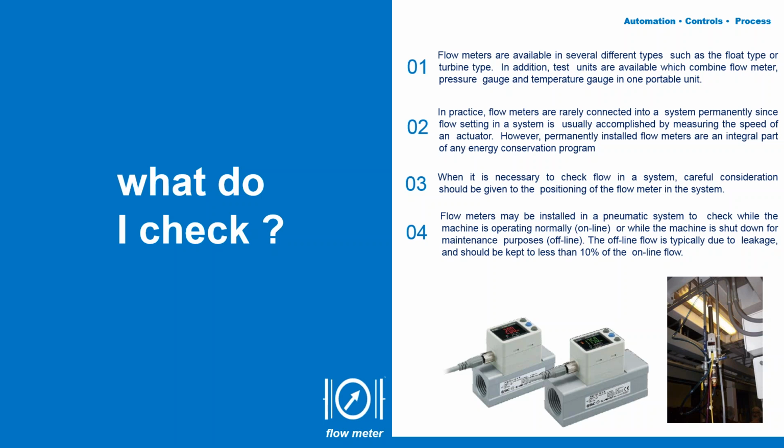As I mentioned, almost every failure can be predicted by the leakage rate. So a machine that has no leaks is very likely running the same way it did when it was new. A machine that has 10 or 20 CFM worth of leakage built in is certainly not going to be performing the way it did before. It might still be doing its job, but certainly inefficiently and probably not as quickly or with the same minimal scrap rate it had before.